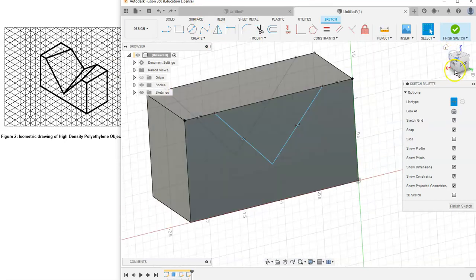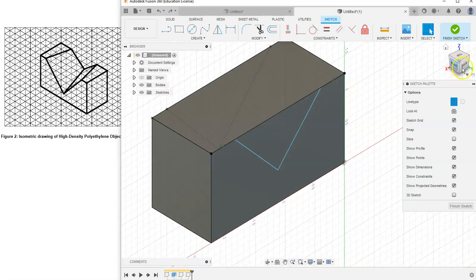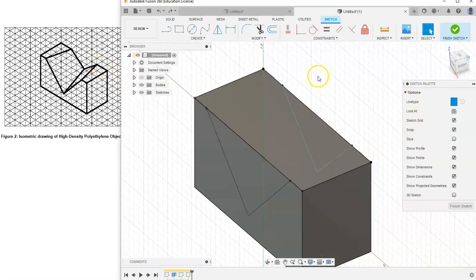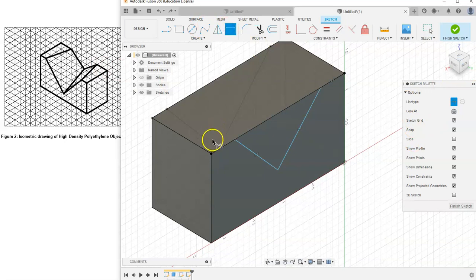So I'm going to go to this modified isometric view from the back instead of the front and take a look. And we could even go over here and look at it from here and say, well, what is the distance between this edge and this edge? Well, it's 2 grids, which is 0.5. So if I look over here, I'm going to give this from this point to this point, if I can find it, a distance of 0.5, which means this side should also be 0.5 automatically.